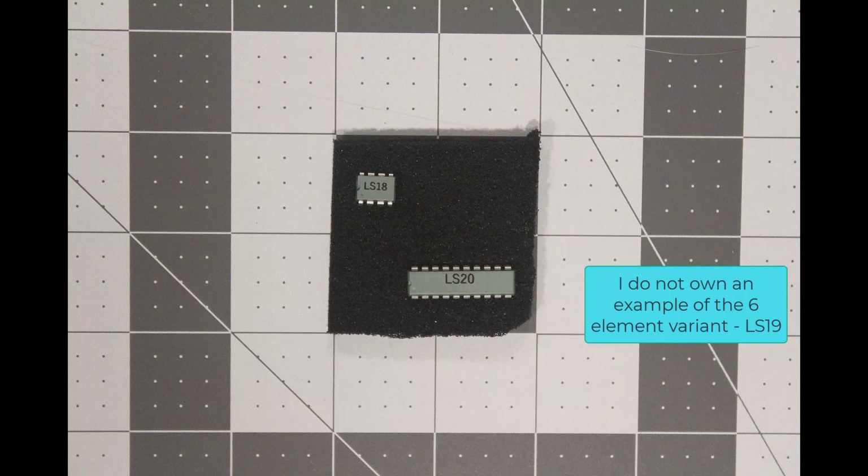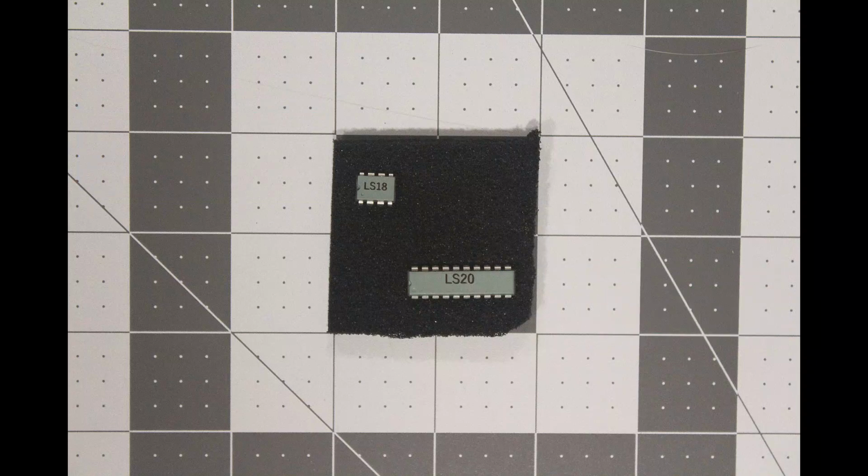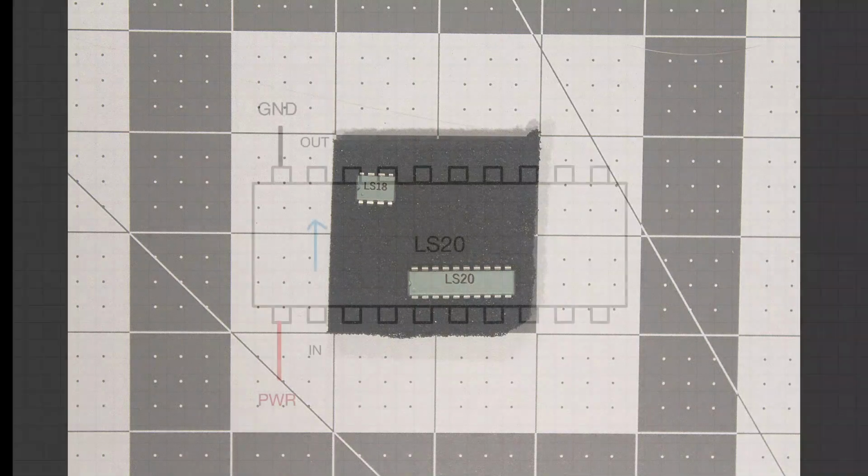The LogiSwitch LS10 series as a solution has the twin benefits of simplicity and reduced pin count as compared to an RC circuit. The trade-off is simplicity over cost, as an RC circuit can be built for pennies in bulk. However, for the hobbyist who is working in low volume and needs a reasonable number of debounced inputs, the cost per debounce element is reasonable, approaching 50 cents with the higher pin count devices. With my projects to date, pin count is my primary budget requirement.